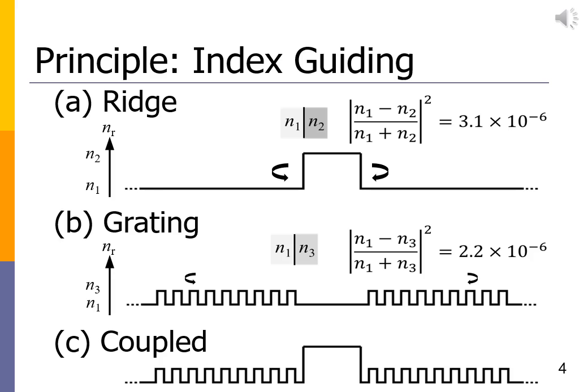Both the ridge structure and diffraction gratings make the light waves resonate. We design the waveguide so that the wavelength of the fundamental horizontal transverse mode of the ridge structure and that of the diffraction gratings may agree with each other. As a result, only the fundamental horizontal transverse mode is confined to the waveguide with optical gain under the mesa.